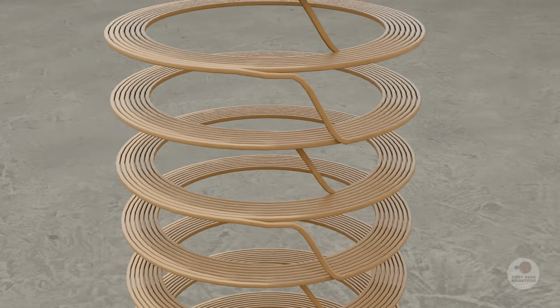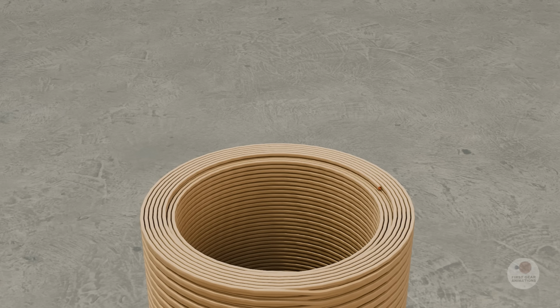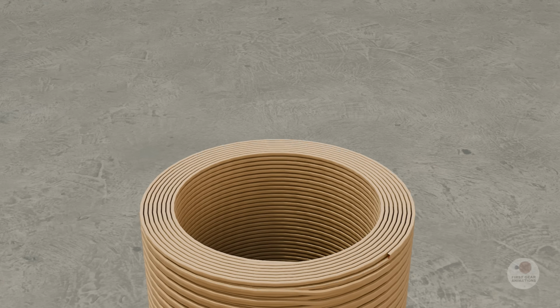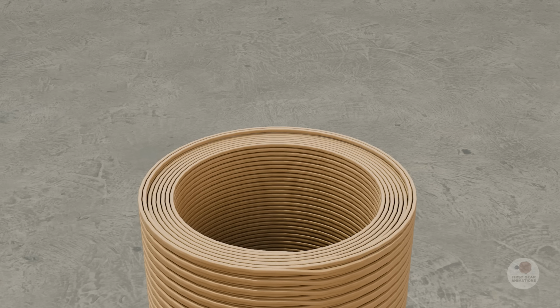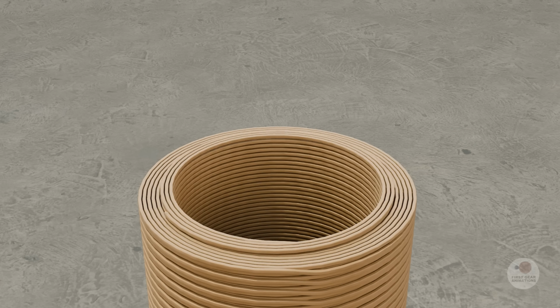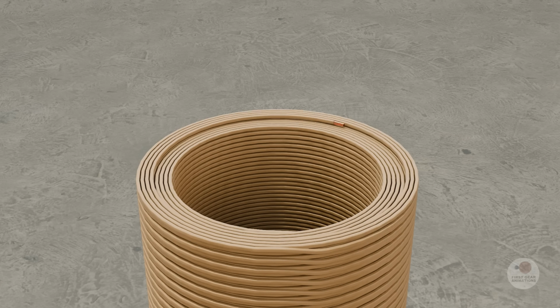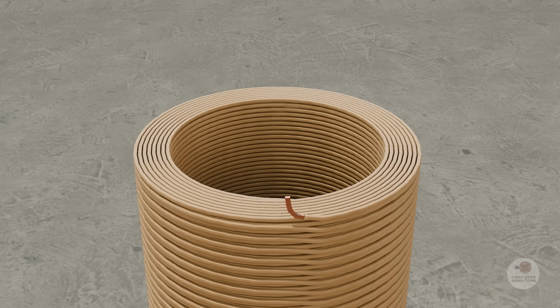In a disc winding configuration, the conductor is wound in a series of flat discs that follow a continuous alternating spiral. One disc is wound from the inside diameter toward the outside, creating an outer crossover, while the adjacent disc is wound from the outside back toward the center, creating an inner crossover. This zigzag pattern creates excellent voltage distribution across the entire winding and gives the coil outstanding mechanical strength to withstand the huge forces that occur during short circuits.